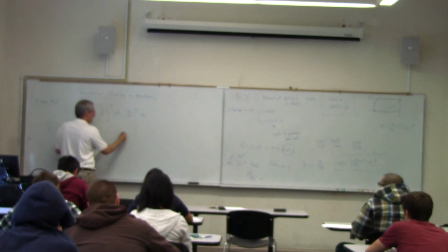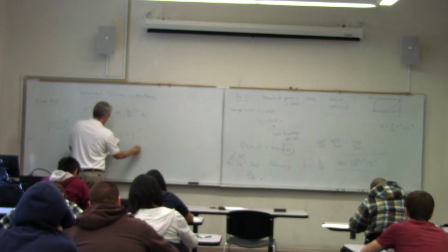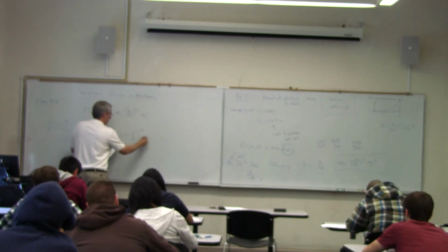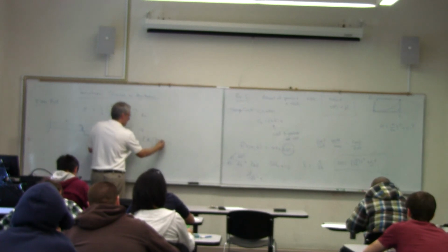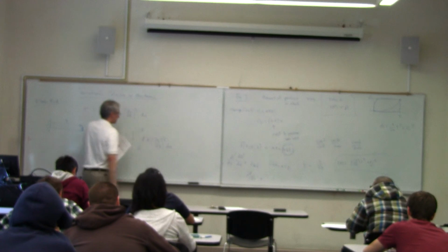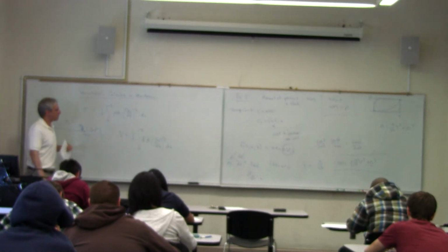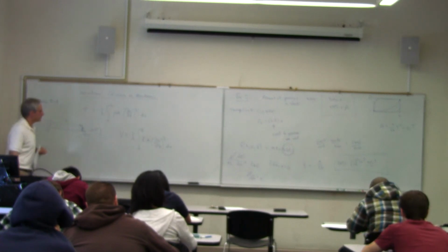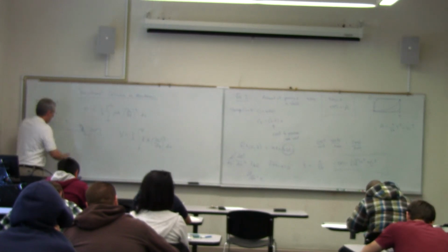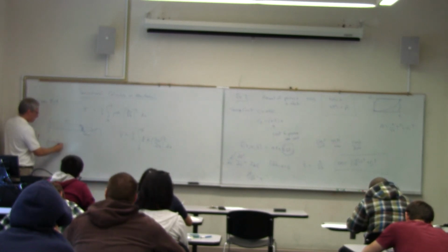And very similar to that in appearance is the potential energy for a continuum rod, and that's EA partial u partial x squared dx, where here E is the elastic modulus of the material, A is the same cross-sectional area, and the partial u partial x is essentially the strain in the bar. So if we go back to the discrete world, it's pretty much like what we've been talking about already,